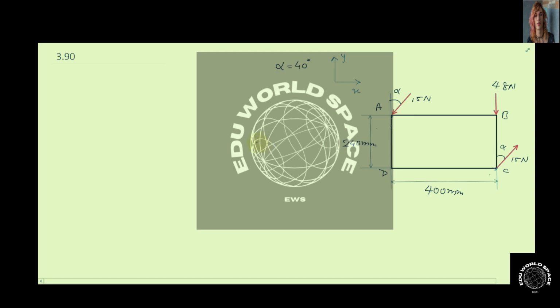Problem 3.90. In this problem, three forces are acting on the system, and we have to replace these three forces by an equivalent single force. For the calculation of the equivalent single force, one can observe that these two 50 Newton forces are anti-parallel to each other because both are making the same angle with the vertical axis. So they will have no effect on the equivalent force because they will cancel out each other.